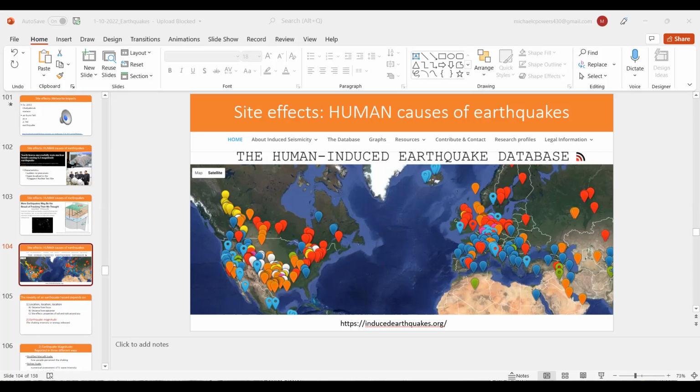All right, and this is our third method of measurement. This is moment magnitude scale. This is the most scientific one we have because it's the absolute size of the earthquake. So we've got a bunch of different parameters. It's the measurement of the actual energy that gets released by that. So you have the rigidity of the earth multiplied by the slip along the fault, which is the displacement. And then we have the area of the fault, which is length times width.